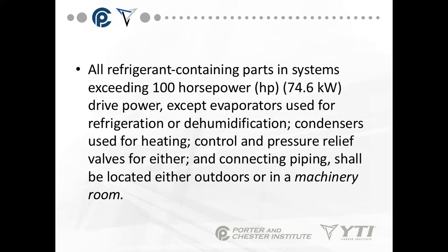All refrigerant-containing parts and systems exceeding 100 horsepower drive power, except evaporators used for refrigeration or dehumidification, condensers used for heating, control, and pressure relief valves, shall be located either outdoors or in a machinery room.